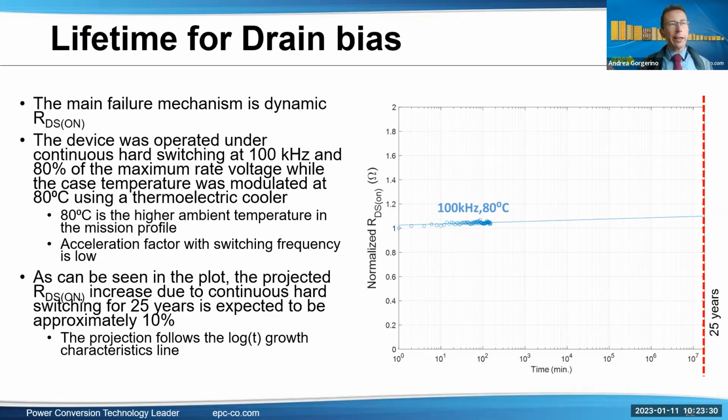In the early days of GaN, like 20 years ago, devices would increase their RDS-on while operating on your bench, and within 10 or 15 minutes, they would get so hot they would blow up. So we've come a very long way since those times. Basically, dynamic RDS-on is not an issue anymore for our latest generation devices at EPC.